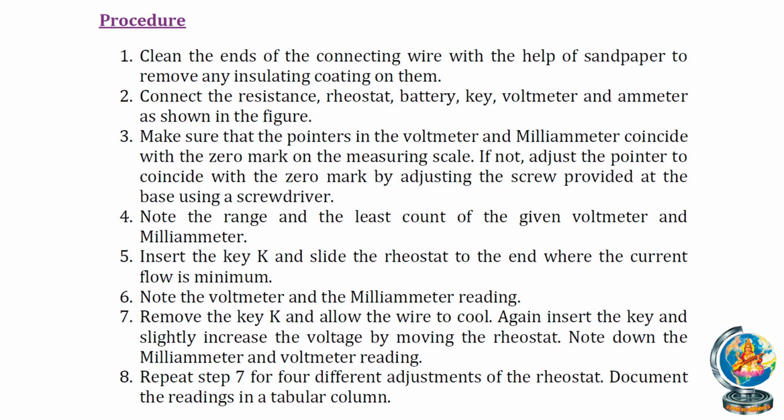After taking one or two readings, you need to give time to cool the wire. Again insert the key and slightly increase the voltage by moving the rheostat. Note down the milliammeter and voltmeter readings again.